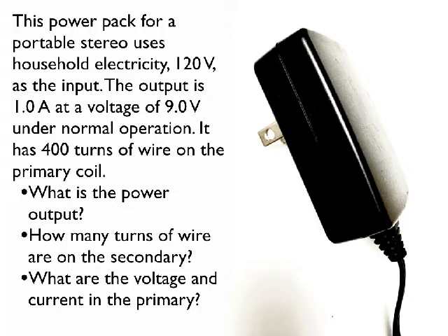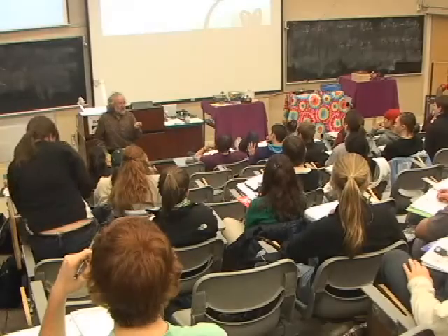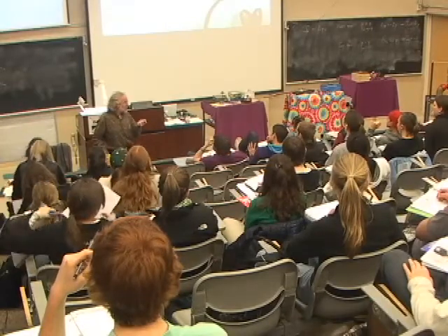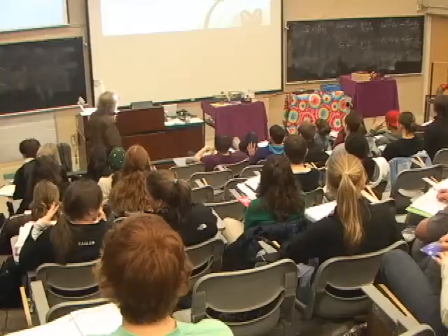And it tells us the output. The output is 9 volts and 1 amp, and it's designed to run at that. It's going to provide 9 volts AC at 1 amp, okay? And typically, electronic devices are designed to run at lower voltages than 120 volts. And so the first stage in them is the power pack. So if you have any kind of electronic device, anything which needs a charger, you have something like this, and it's a transformer. The voltage decreases here because it goes from 120 down to 9. That's more typical.